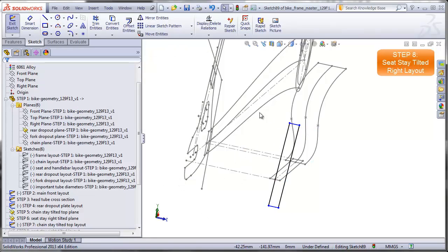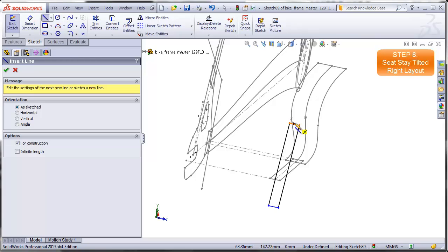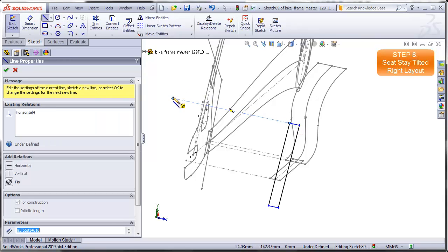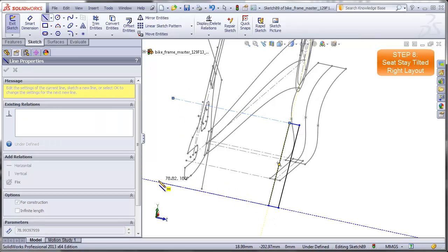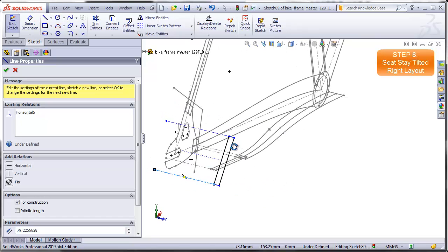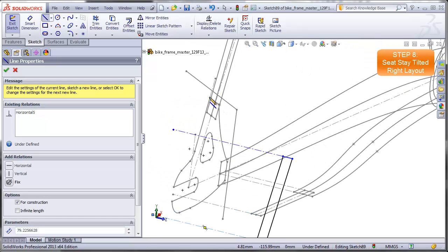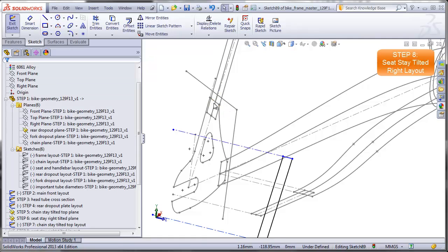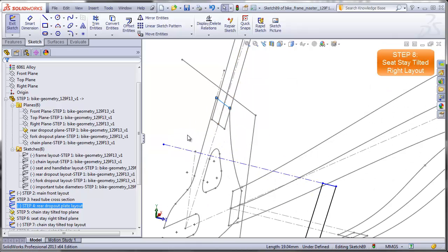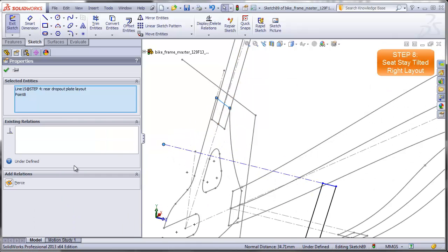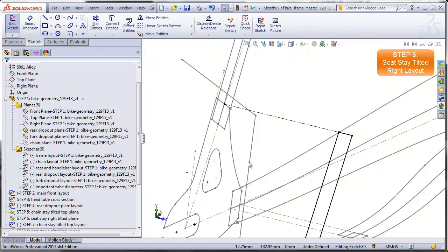I want to align the top with the top here and the bottom with the bottom here. So once again using our trick of adding a center line, this time they'll be horizontal. This top center line needs to be aligned with this line here. The best way to do that in this case is to use a pierce. So just click on this line, click on this point, and make a pierce.